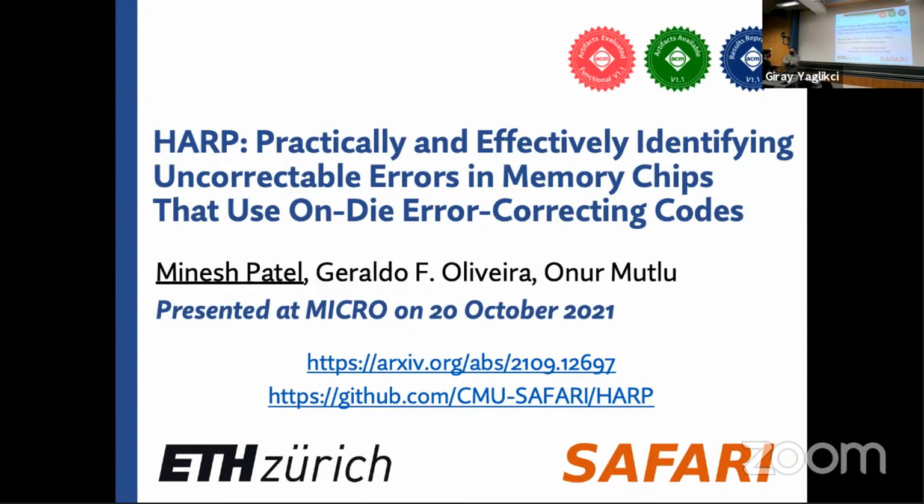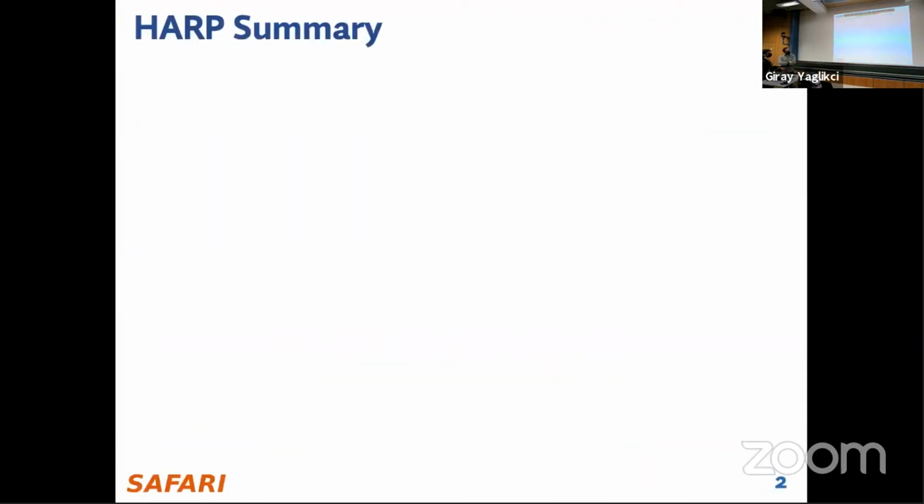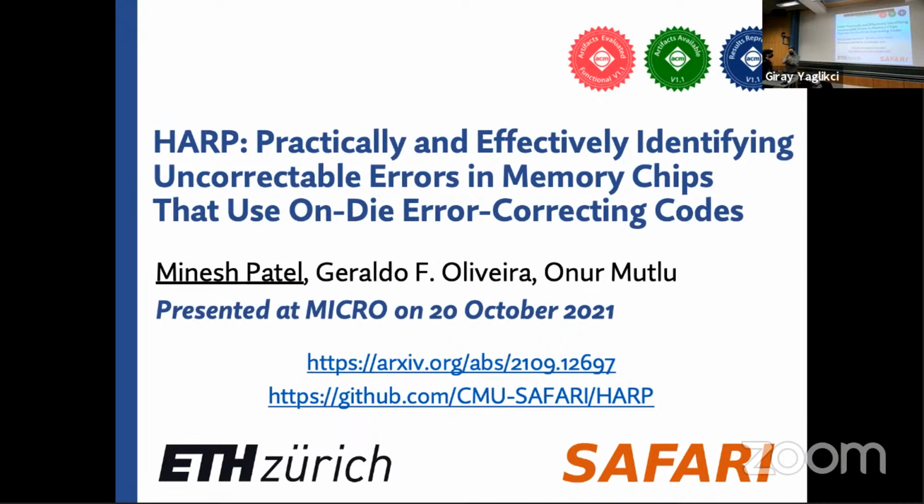And Giray in the paper shows that it's accurate. And always, I think testing more workloads would help. That was part of the discussion. I don't know if a lot of work covered benign workloads, but there's certainly anecdotal evidence. This is not published, but anecdotal evidence that there's some very, very rare workloads that induce RowHammer bit flips in real systems. But this, I think we discussed this in one of the RowHammer lectures, but this is anecdotal